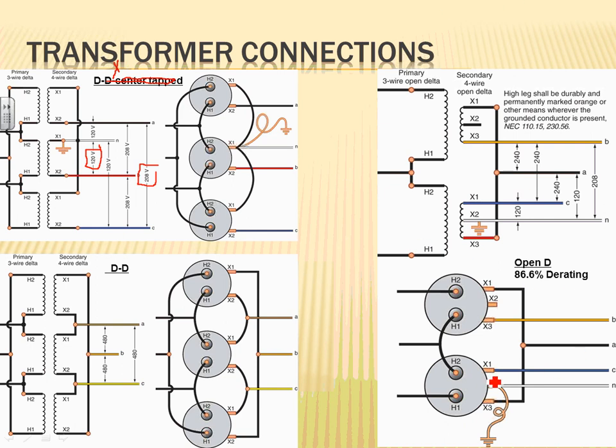On the secondary side, they take one of the transformers, which is typically the fat transformer. So this typically will be, say, 75K right in here, and this typically 50K. So one of them is bigger than the other. One of them is 50, the other one is 75. So the 75 guy can have extra 25 kW for the line to neutral load. Line to neutral, they call it line to neutral load.